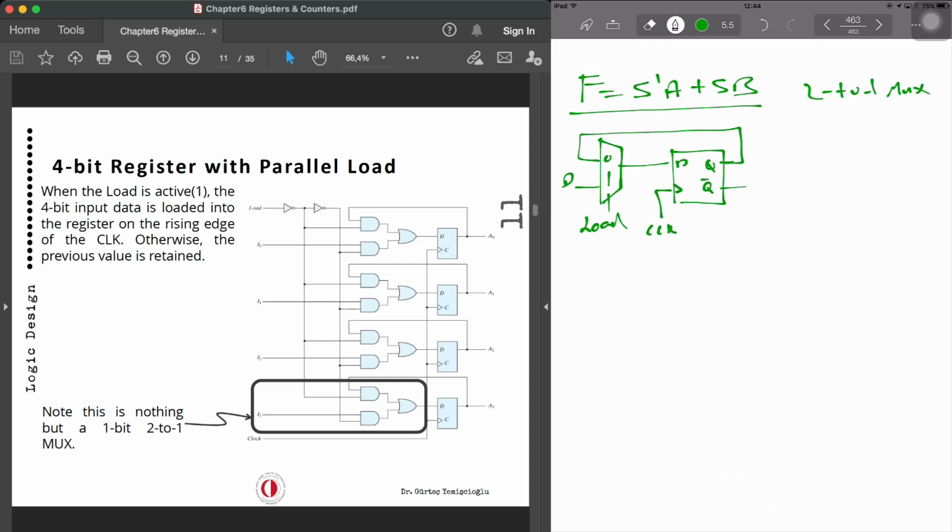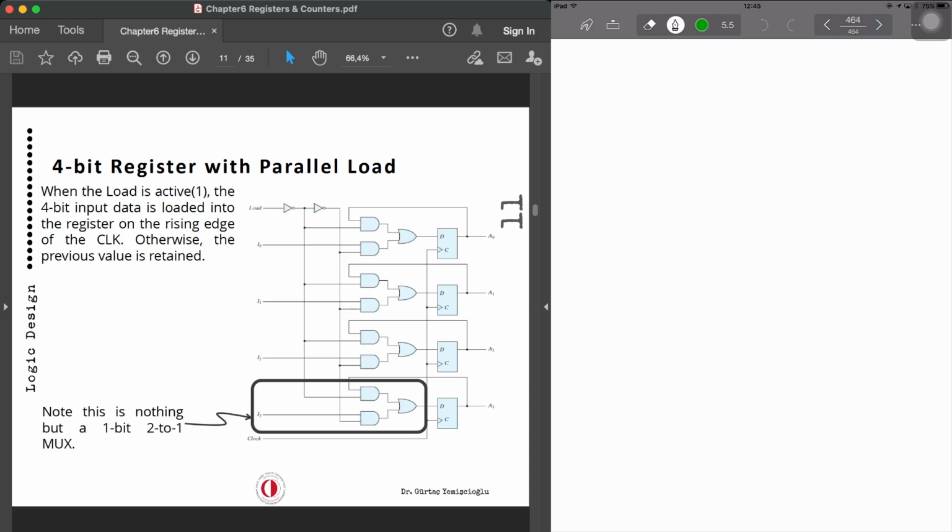Now there are different types of applications where we use flip-flops in order to design registers or maybe a shift register, which is another one of the most used devices in logic design. Now, a 4-bit shift register, for example, if you want to demonstrate this, we need flip-flops, 4 of those again.